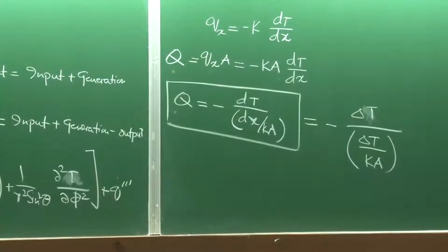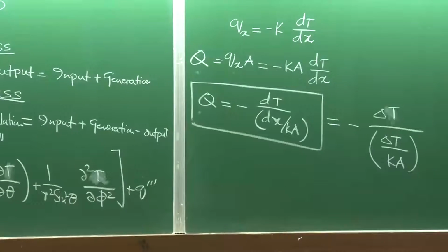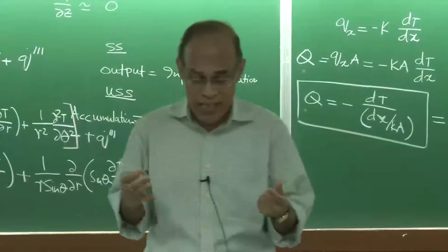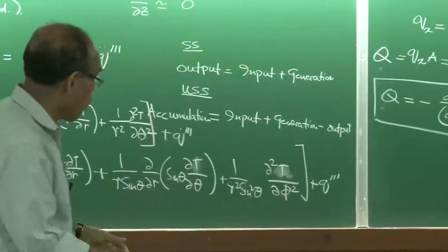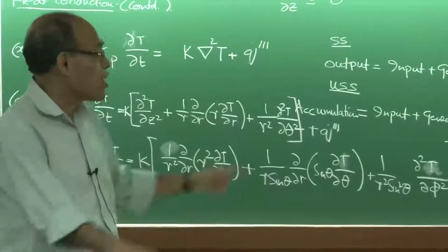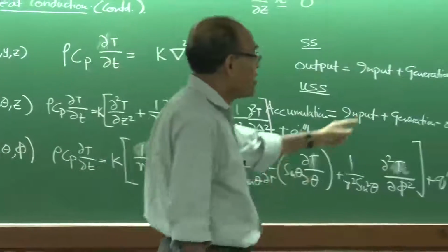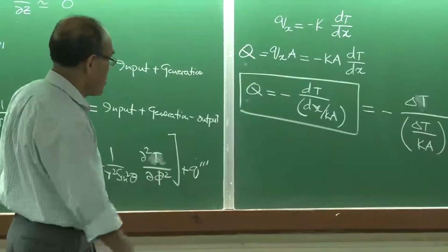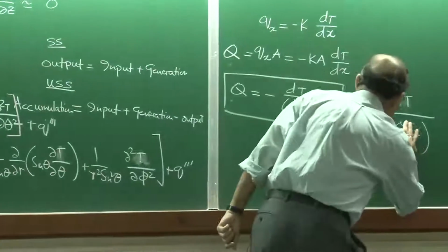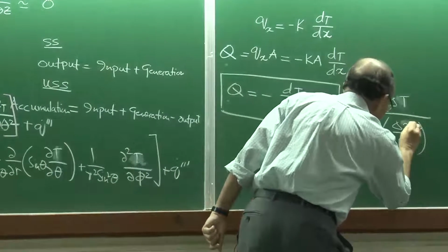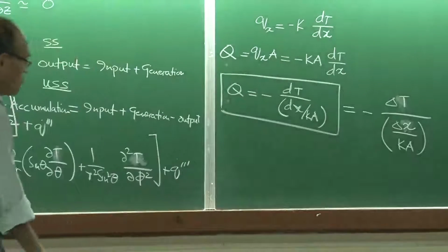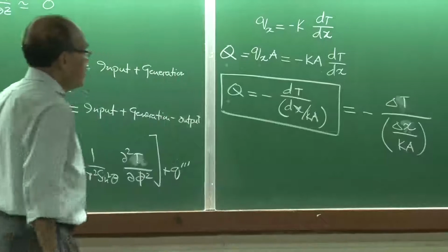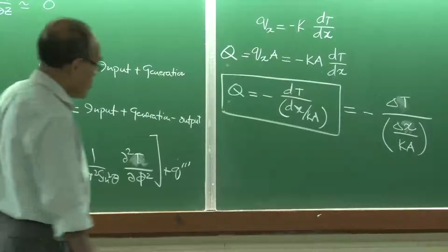circuitry, you see that there is one-to-one correspondence between Ohm's law and Fourier's law. In the context of Ohm's law we find that it is potential difference. The current is flowing because of the potential difference, and the proportionality constant is the electrical resistance, and in that case what we get here is nothing but the thermal resistance. Okay? So, this term, let me correct it, yes, on the denominator represents essentially the thermal resistance of the system.